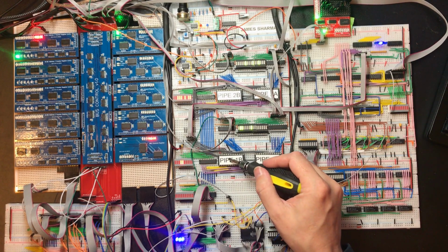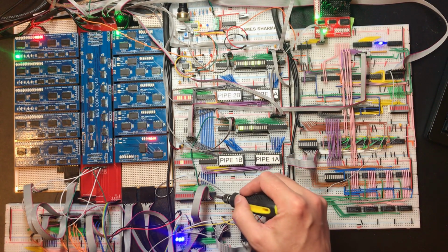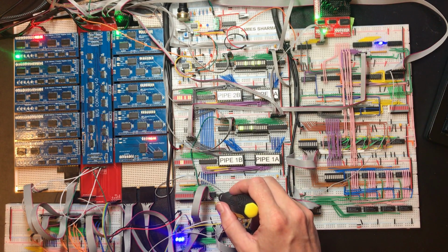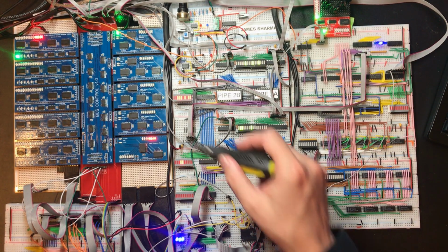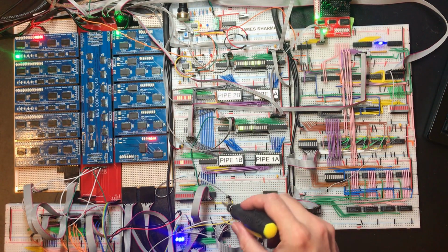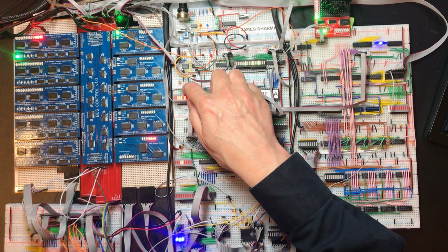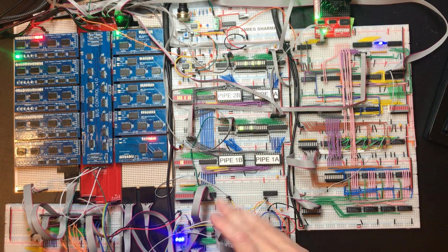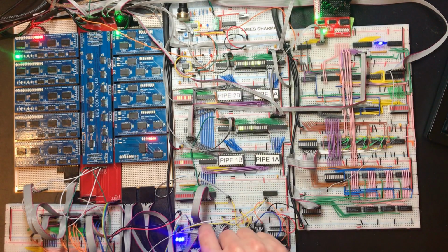The jump instructions are being processed here in pipeline stage 1, and the fetch here is what's causing us the problem. We're trying to read an instruction in, and then this little setup here is causing the program counter to get incremented. Now we do have this line here. The bus request line is a way of suppressing the fetch and increment. And it's just the increment we would like to suppress. But this line goes to both.